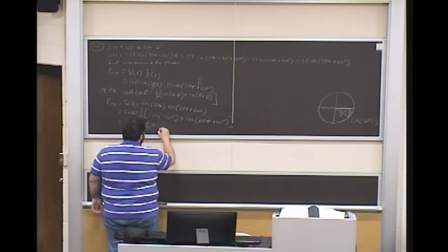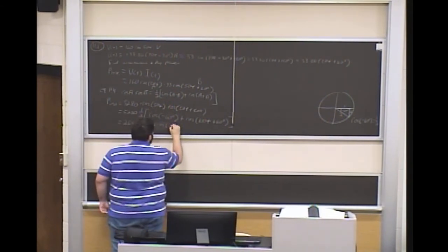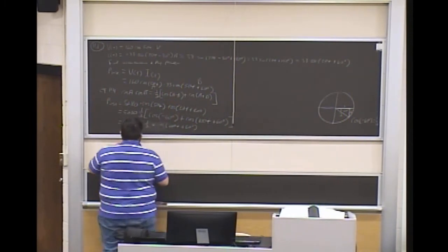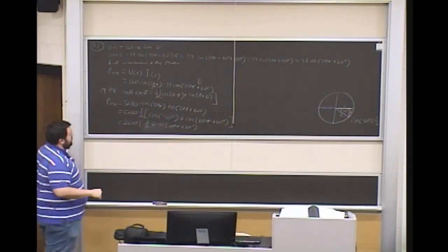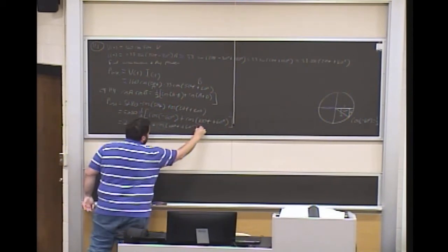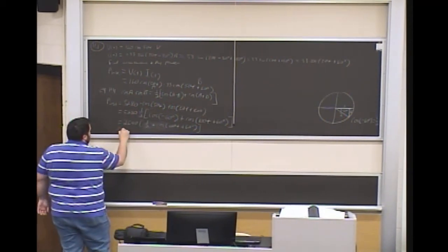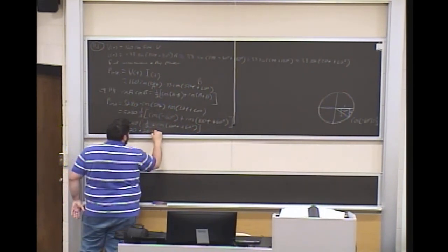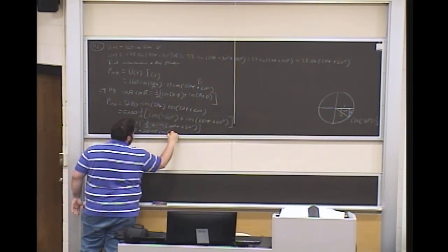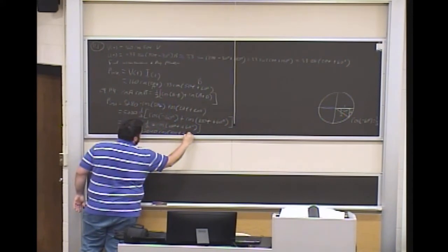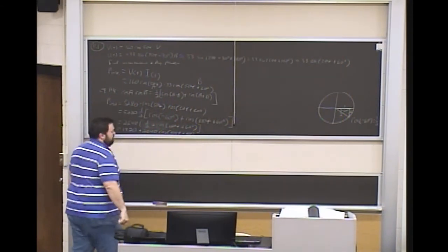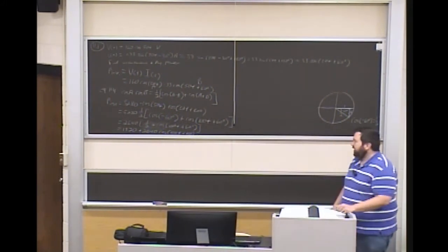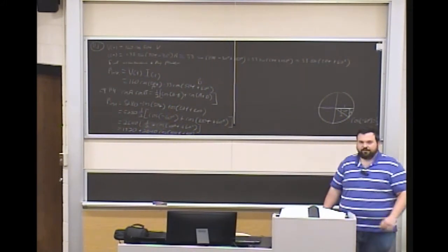So we're going to replace this with 1/2 right in here, plus cosine of 100t plus 60 degrees, which we'll leave the same. And if you distribute this on through, this just gets divided in half again, so you get 1320 plus 2640 cosine of 100t plus 60 degrees. Okay? So that is our instantaneous power.